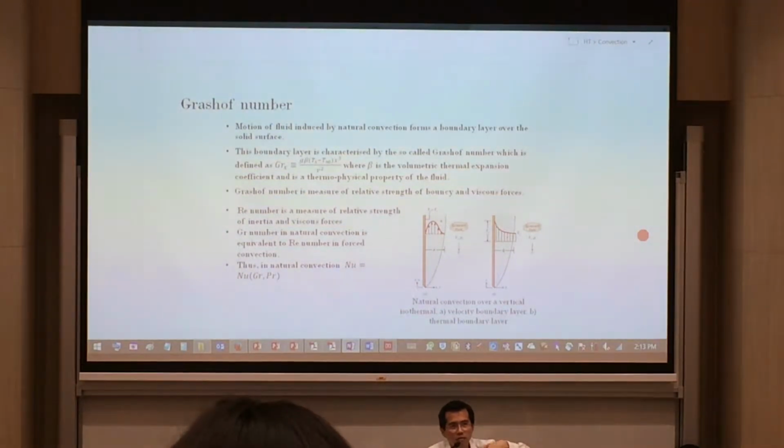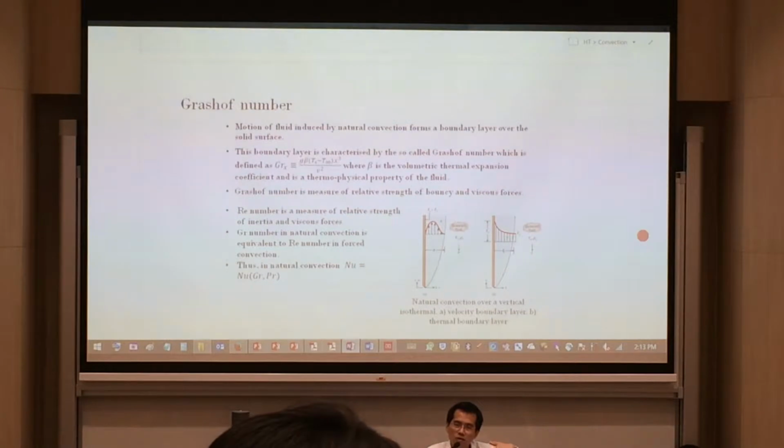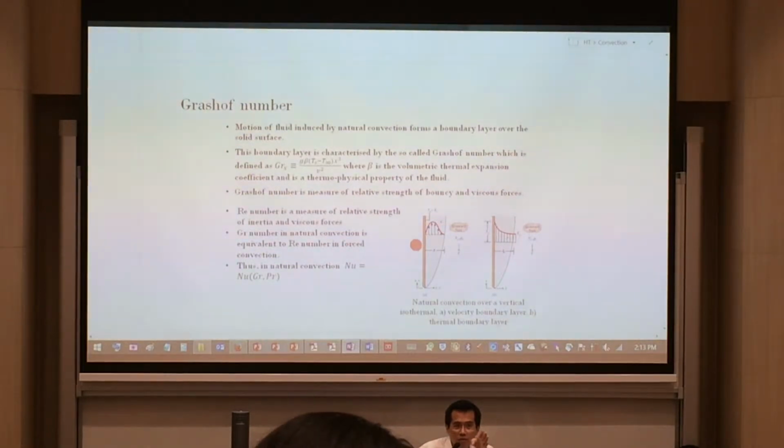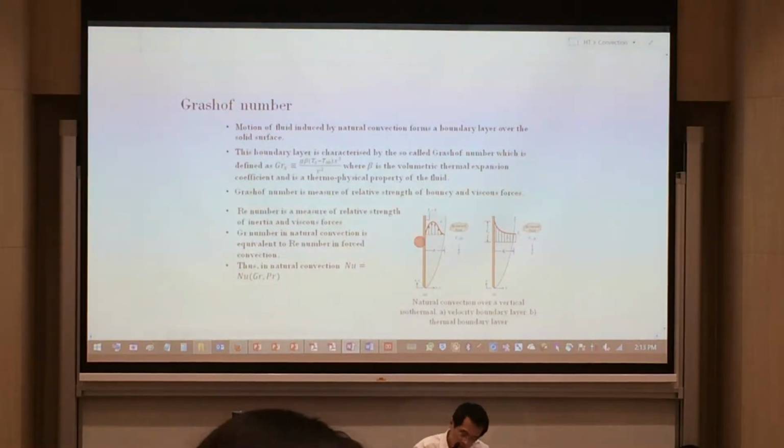And now we're in the topic talking about natural convection. So for natural convection, we would know that the flow is going to go up due to the fact that, let's say, in this case, your plate is hotter. So if the plate is hotter than the ambient, you would see that the air layer that's right next to the plate will get heated up, and then it will become buoyant, and then you will flow upward naturally. And we have seen before that the velocity that's near to the plate will be zero, and in this case, the quiescent fluid, that means fluid that is stationary, not moving, we call that quiescent fluid.